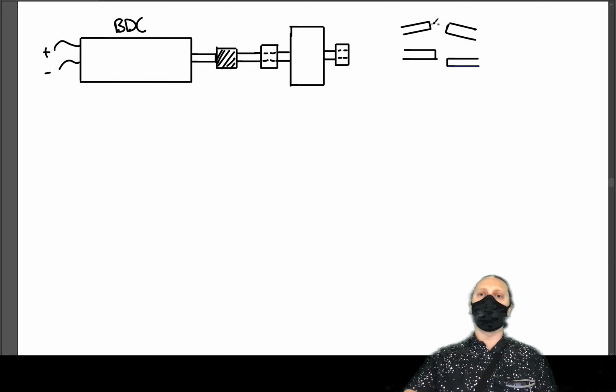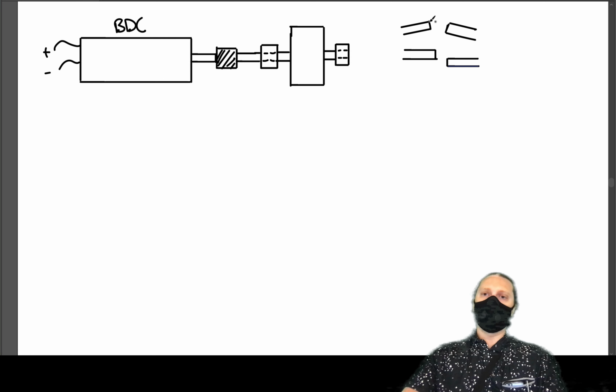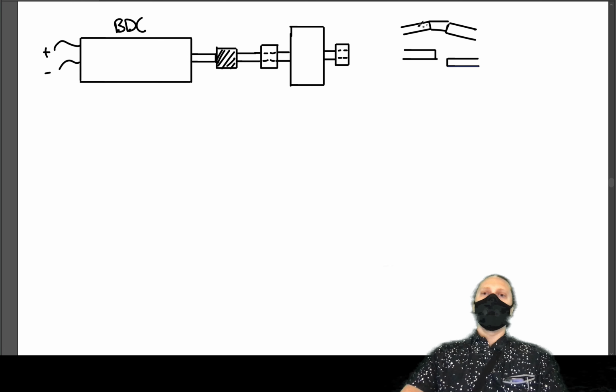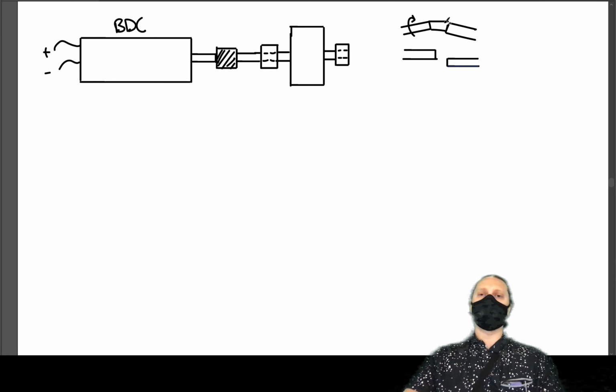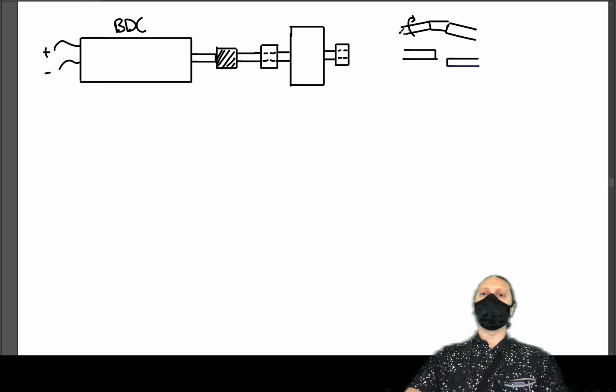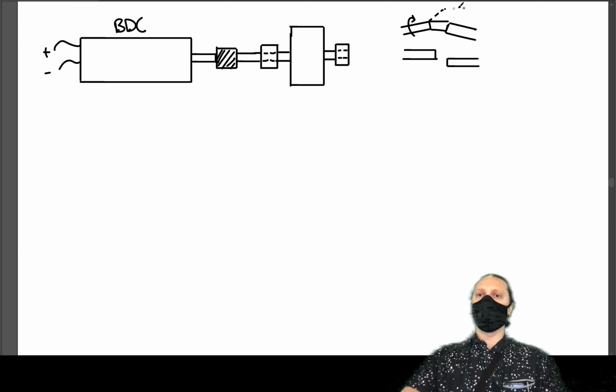So say you totally rigidly connected these two together, and you start turning this shaft. Say this shaft is the power shaft, and this one's supposed to follow. Well, if this one stays perfectly aligned with its axis, then as you turn it around, the other one is going to end up over here. If I mirrored that, this is where it would want to go.